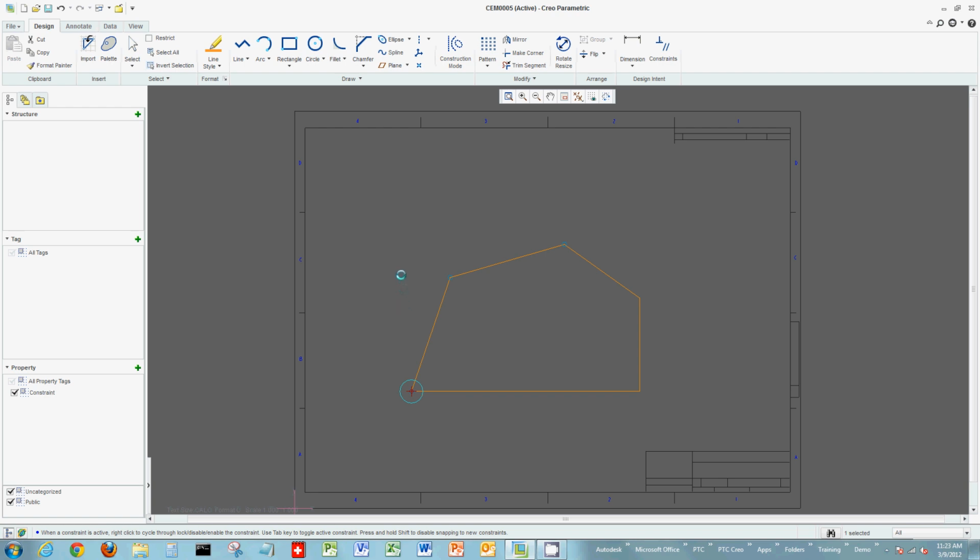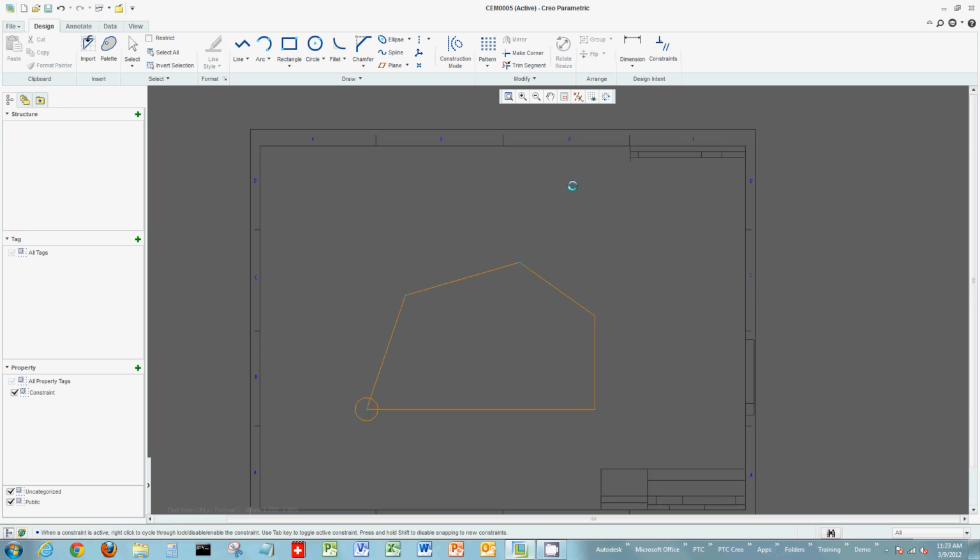Again, just pausing wherever that endpoint is, that element is now snapped to that endpoint, picking up that constraint in this example. Some other techniques, using aligning. So if I, for example, start a line from this point, and I temporarily pause where I see my alignment constraint, I can now drag, and I have an alignment of this new entity I'm creating. Again, I can have equal length lines, or I can key in values in my different types of units, what I'm actually trying to create in this example. And then snap. So these are a lot of aids placed in to assist with creating entities.